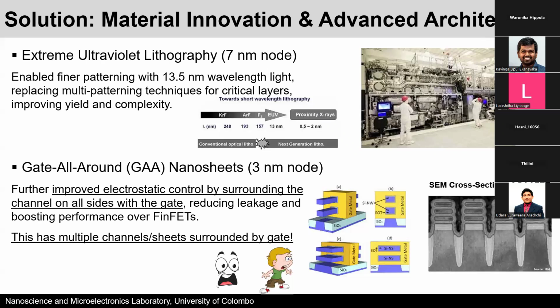And it's pretty hard to get around these brick walls because these things actually arise from fundamental physics, right? If you have X-rays, the X-rays would travel right through the optics and also through the silicon wafer, and then you cannot expose anything because X-rays can go through materials, right? So that's why we are somewhat stuck here in this regime, and the best we can do is the extreme ultraviolet, which has a wavelength around 13 nanometers, right?